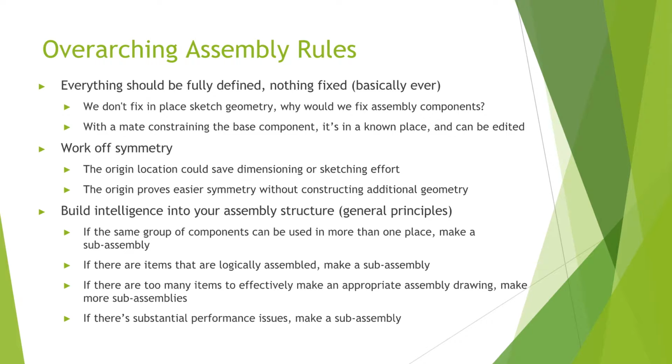Overarching assembly rules: everything should be fully defined, nothing fixed. Now, a lot of what I see is the first component in your assembly has a little F by it. It has the F by it because that's what SolidWorks does by default. And of course, that's what SolidWorks does by default, so it must be okay. Right? Except there's like 30 other SolidWorks defaults that we all hate and curse at.